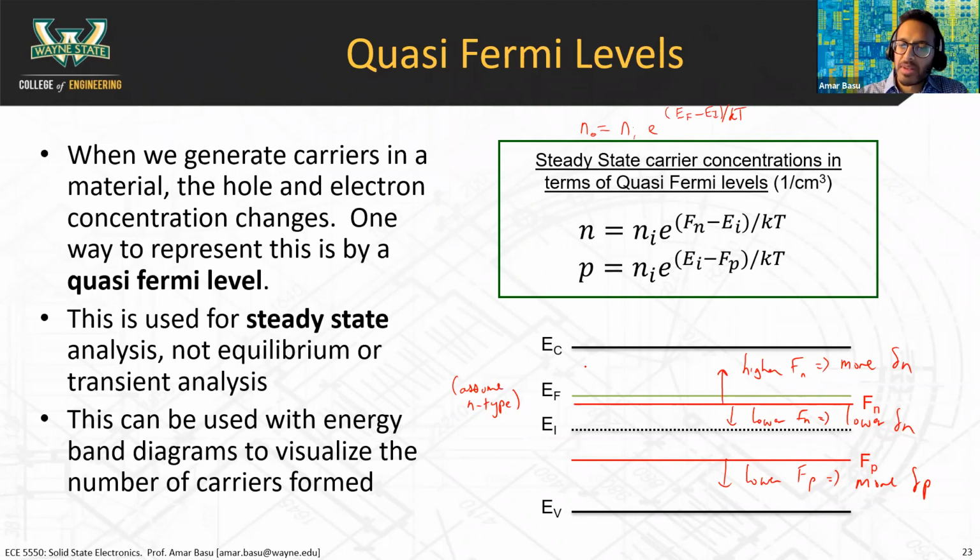That's right. So basically, like that intuition, I look at the energy band diagram and I see where E sub F is. And in my mind, I'm thinking, well, the higher E sub F is, the higher the Fermi level, the more N-type the material is. Similarly, with F sub N, depending on where that quasi-Fermi level is, I'm thinking, well, how many extra electrons did I add into this material by shining light on it?